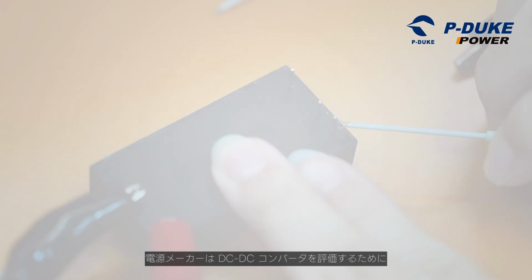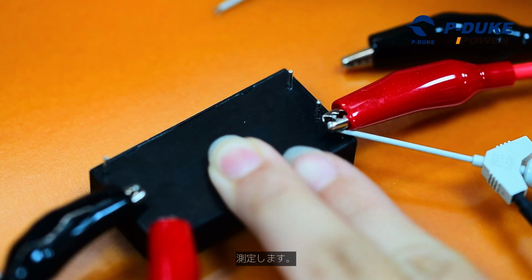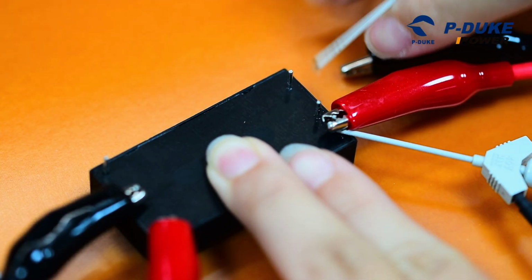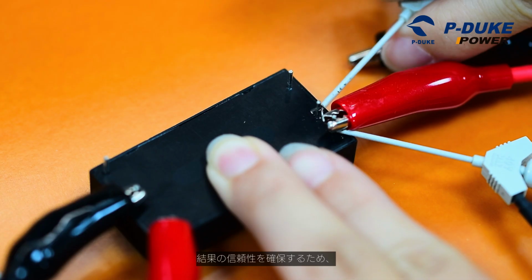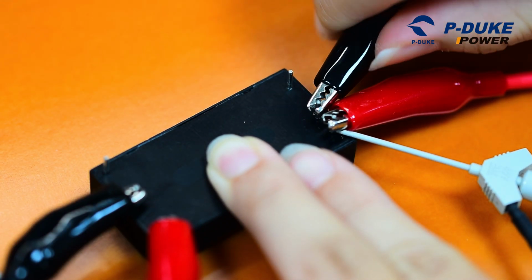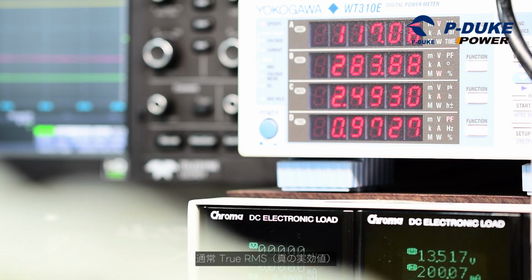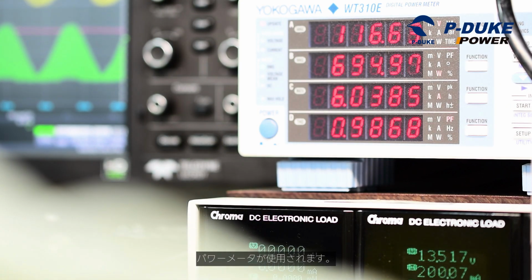Efficiency is accurately measured by power supply manufacturers using a specific setup to evaluate DC-DC converters. Precise voltage readings are taken directly at the converter's pins to ensure reliable results. The setup for AC to DC power supplies is comparable and typically involves using a true RMS power meter.